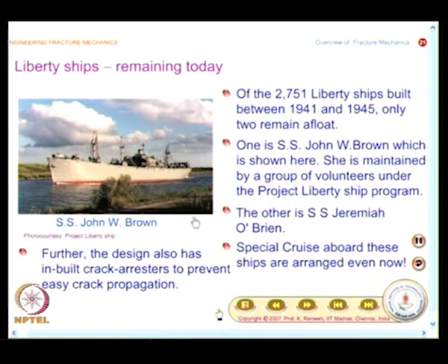And if you look at the modern development, the ship steels in the middle of the 20th century had this NDT as something like 10 degrees centigrade. Now it has been brought down to something like minus 4.5 degrees centigrade. This is one aspect of it. That means when there is a failure, you improve the material. People have studied the material and have been able to bring down this nil ductility transition temperature. So, the new steels are like that.